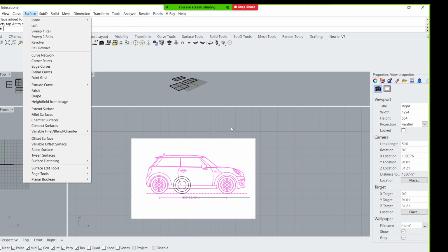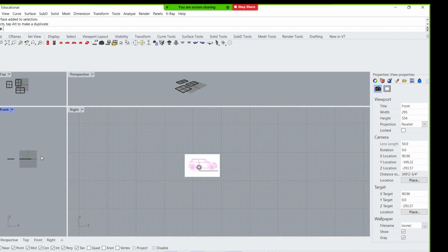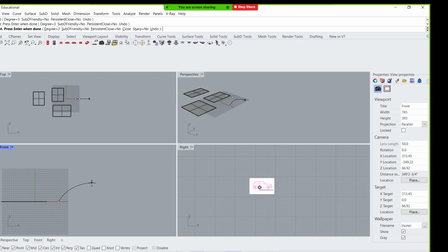So those are kind of the main plain surface tools, and that top bit. Now we touched on this a little bit last week. We'll talk about the loft, just briefly talk about the lofting tool. I don't know if you all know, but my ortho is on. F8 is the shortcut to turn your ortho on and off. If you ever need to use shortcuts, I'm a very big proponent of the shortcut.